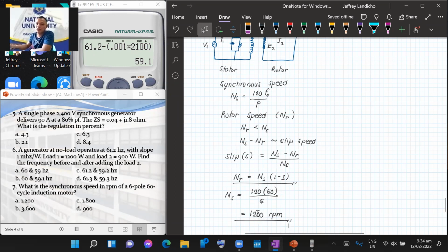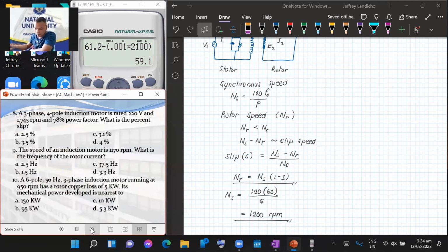So, kapag nakita mong speed end with those 2 zeros, automatic synchronous speed yun. Kasi yung rotor speed, kumbaga, ito yung merong butal, may gansal. Hindi siya exactly divisible by hundreds. But synchronous speed, it is always divisible by hundreds. Okay? So yun ang relation between synchronous and rotor speed of this induction motor.